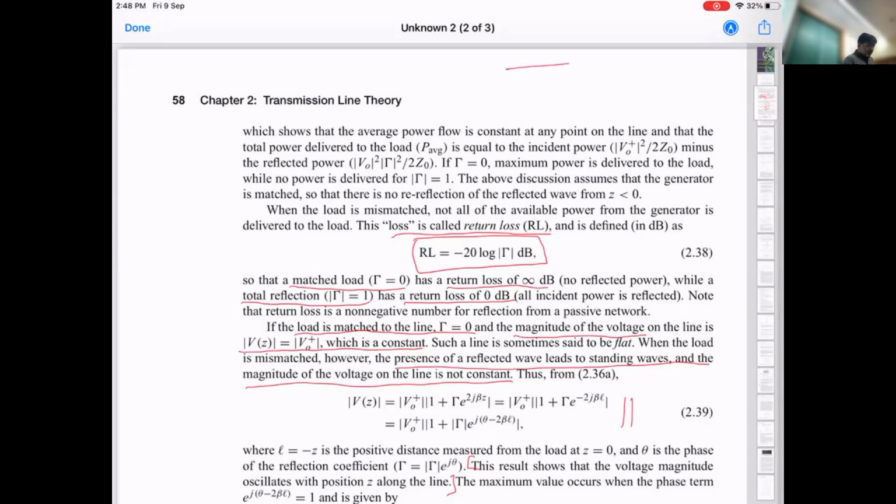What I'm asking is that you have a transmission line of Z0 and it is terminated with some resistor R, which is close to Z0. If it was exactly Z0, you have 0 reflection. So how much can R vary in order for the reflected power to be less than 1%, which is this figure of merit we just mentioned?